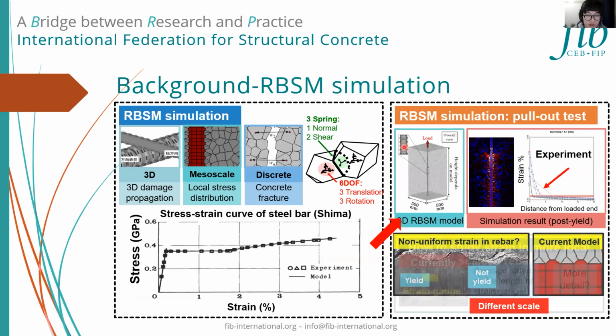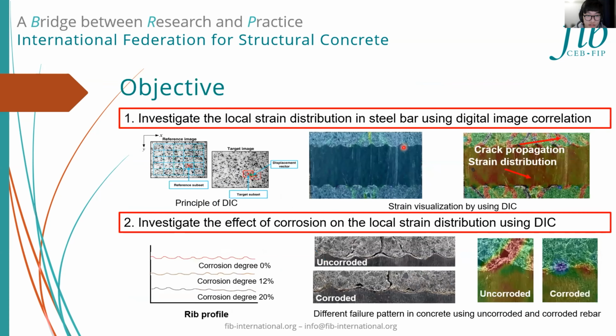Yes, as we carefully checked the initial pictures for analysis, we observed that in the steel bar there are already some white and black points inside. So there is no need to attach new white and black points to increase the accuracy. I see. You didn't need to use any spray or something to make a speckle pattern. Just the patterns of the rebars themselves work.